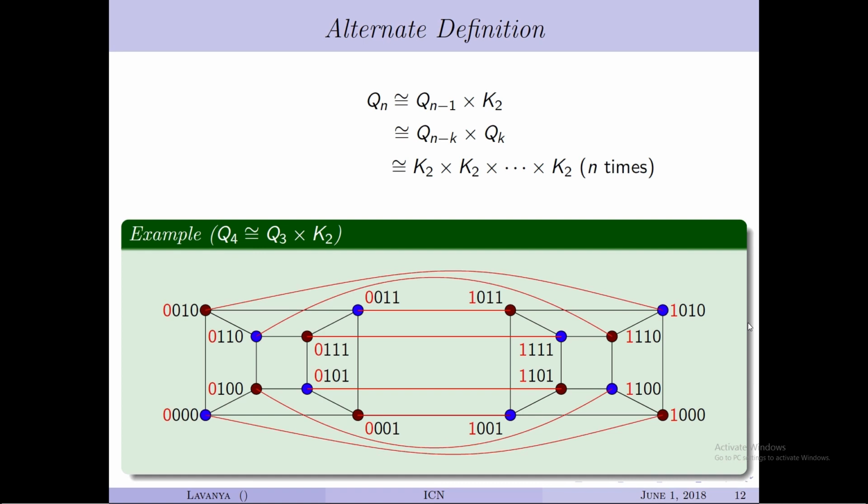Can I put that? See, at least in this you can immediately see that these two cannot go into the same partition. But in your binary labeling, you pull out all the nodes which have an even number of ones into one partition and an odd number of ones into the other partition. So, that will obviously give you 2 hops, what you are looking for. Actually what we want to say is the difference should be at least 2 to come into one partition, right.